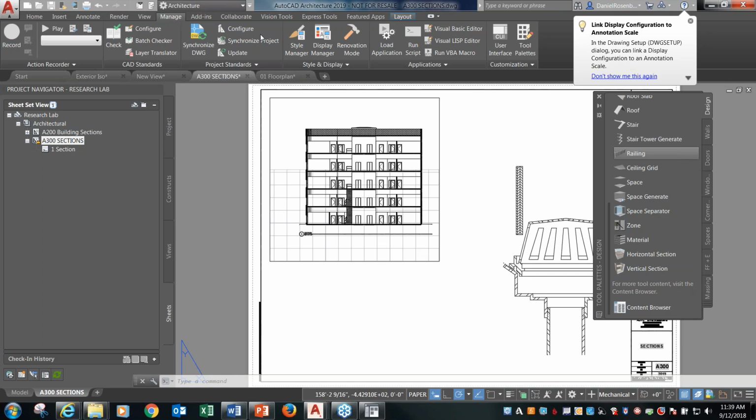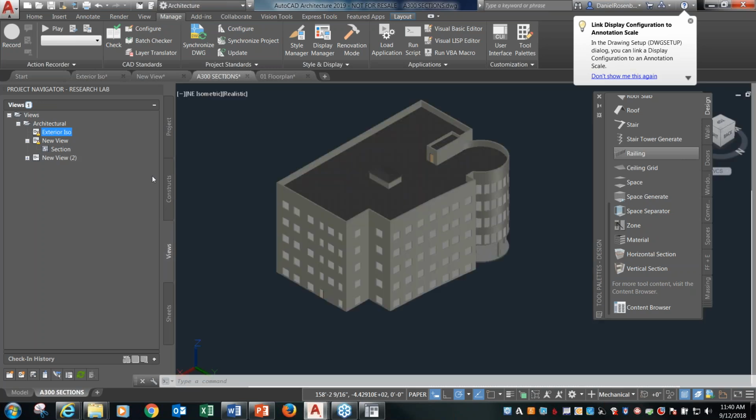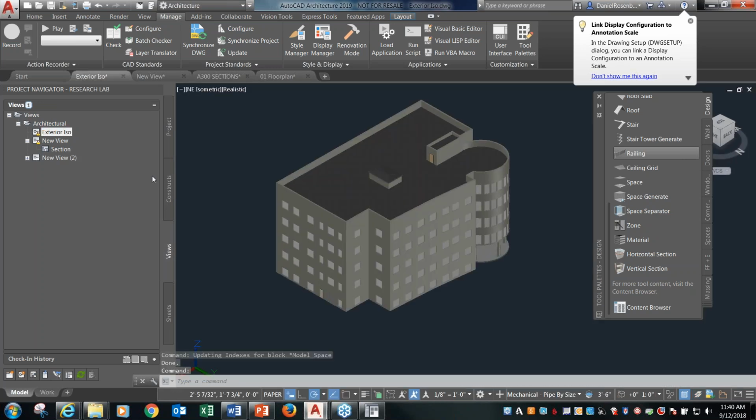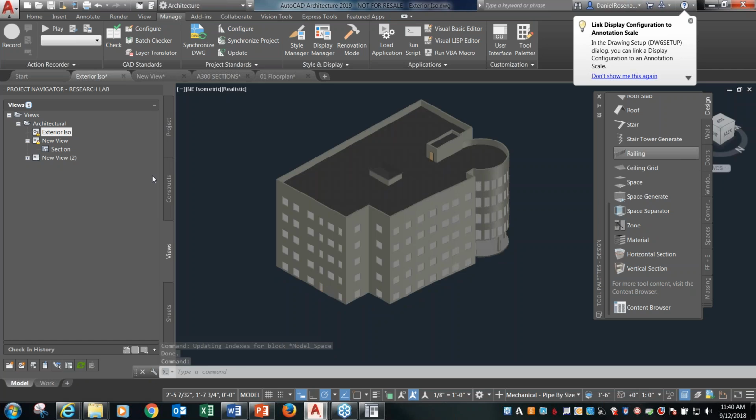How can you work as a team? Again, it would just be working on individual drawings. If you can divide it up into several different constructs, like in this particular one, each floor is a different construct. When you get into different views, one person could be working on a construct while somebody else is working on the view, because it's using XREF. So if he makes a change in the construct, you just get a message saying update that view. So it'd be each person working on an individual drawing, no two people working on the same drawing.